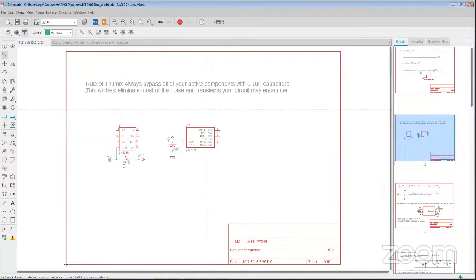Now what do we mean by weird or erratic performance? Basically stuff that you can't explain. If any of you do software, if you've ever programmed a microcontroller and your stack overflowed, that's what we're referring to by erratic behavior, just complete nonsense that you can't figure out why it's happening. One of the things you may want to check is your decoupling capacitors.